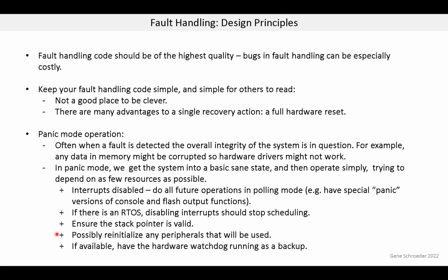Possibly we should reinitialize any peripherals that will be used, for example the UART. Now, I didn't do that in this course because of the way the hardware initialization code is organized right now, but it's a good idea. And then finally, if available, have a hardware watchdog timer running as a backup. So if something goes wrong and your fault handling gets stuck or whatever, the watchdog will hopefully reset the system.